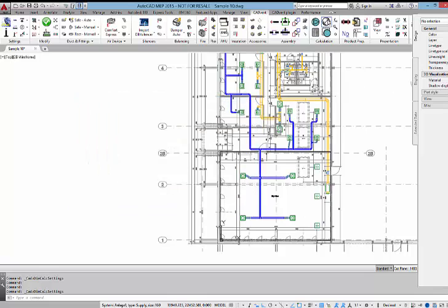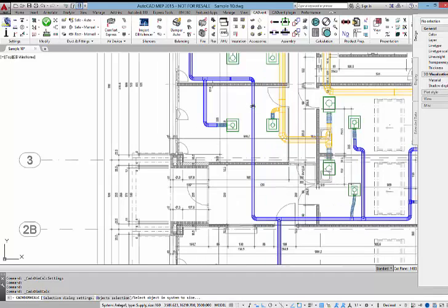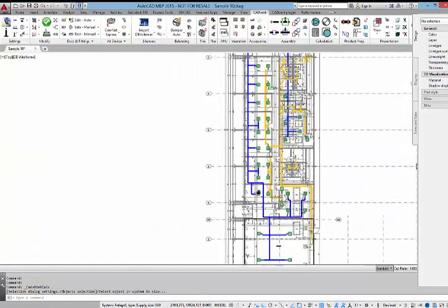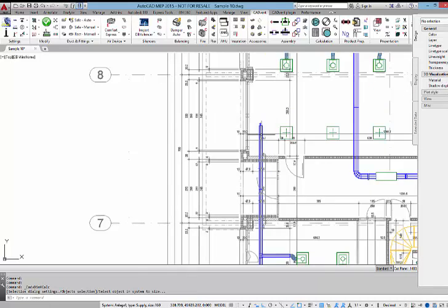With these sizing functions, I say to the system, please size now. So, and you see, there is no tree, it says. No tree means I have no start point. Here's an open end. This open end can get a signal to be used as a start point, and this is this symbol here. And now the system knows, here the air gets in or gets out, depends on supplier or extract.